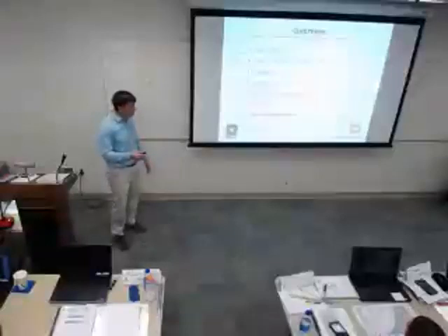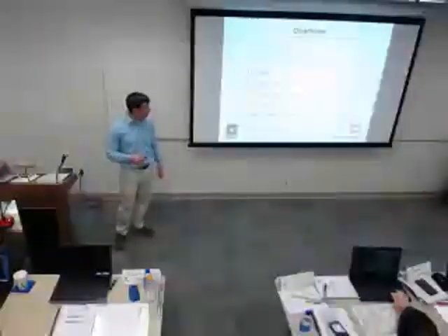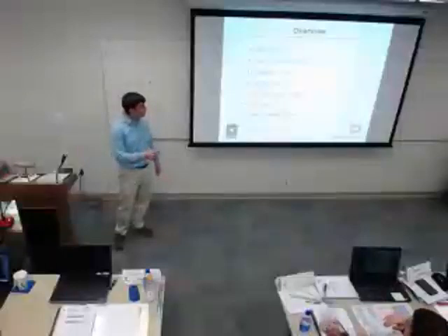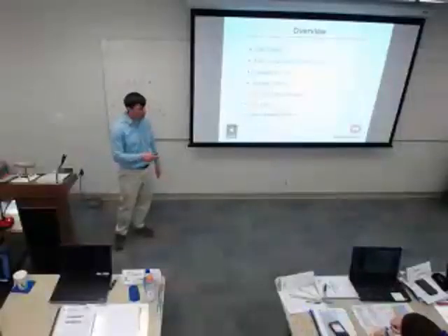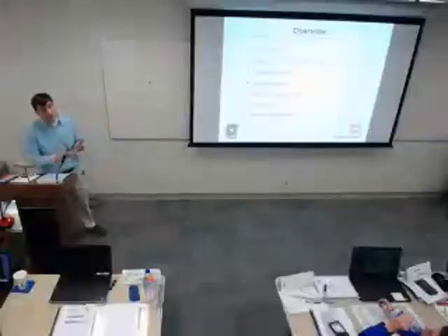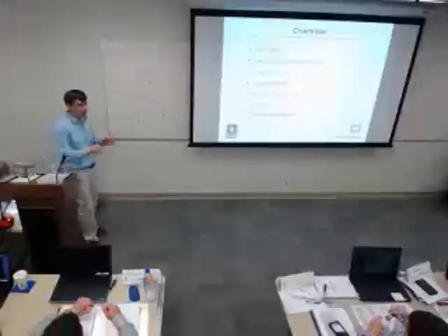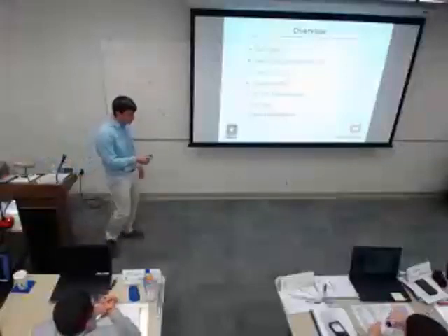We're going to talk about fan terms again. We showed you a slide earlier as far as the actual construction of a fan. Got to touch back on the fan curve, and like I said, add a system curve to it. The system curve is dictated by the physical characteristics of the system: duct sizes, the number of elbows, dampers. That's how you come up with a system curve. I'll show you more of that in a minute.